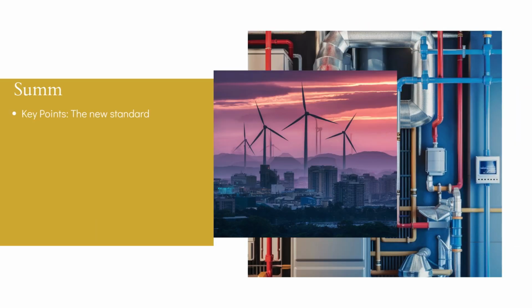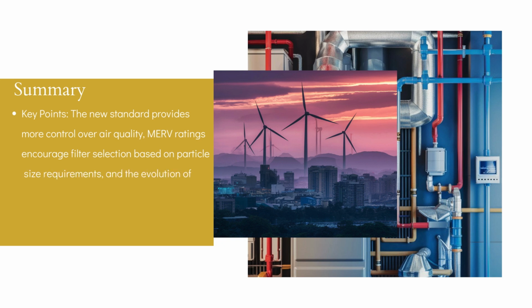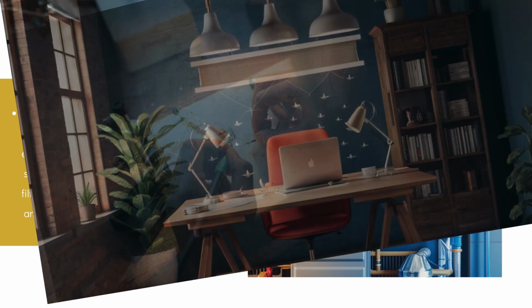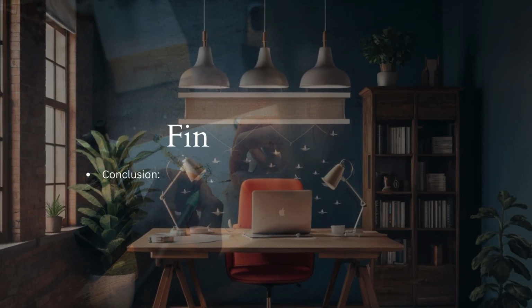The evolution of air filtration standards has led to more precise and accurate testing procedures. ASHRAE Standard 52.2 grew out of ASHRAE Standard 52.1, 1992, which developed out of Standard 52, 1968. Prior to Standard 52, 1968, air filters used in facilities were large mesh furnace filters that kept large fibers from fouling heating and cooling coils.